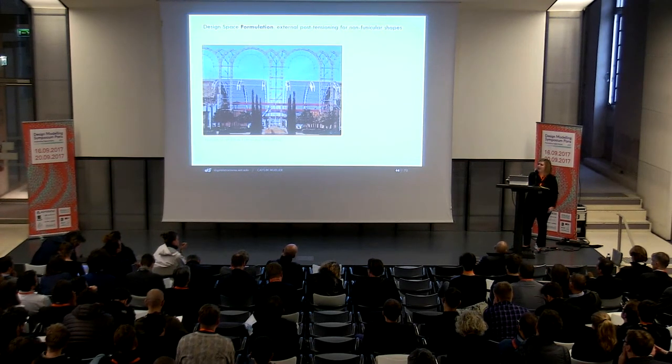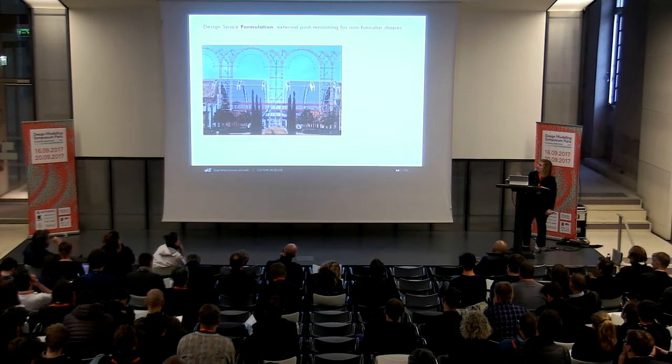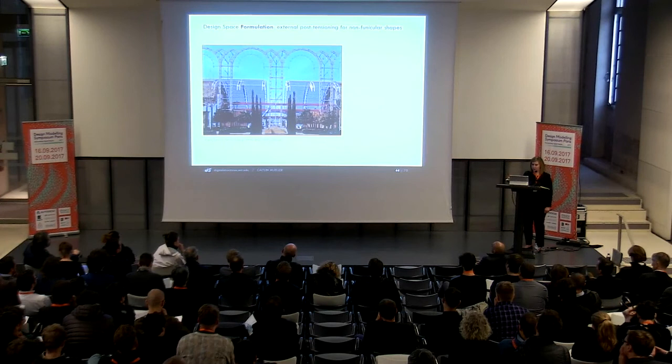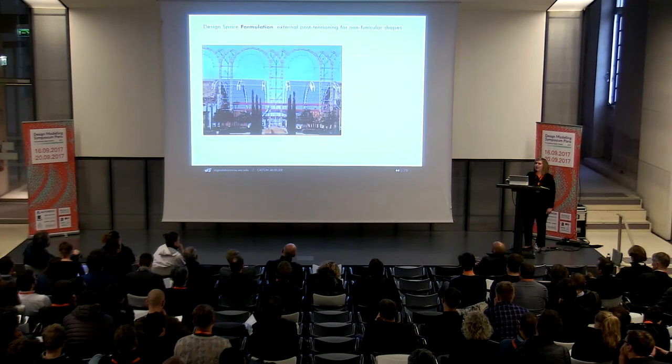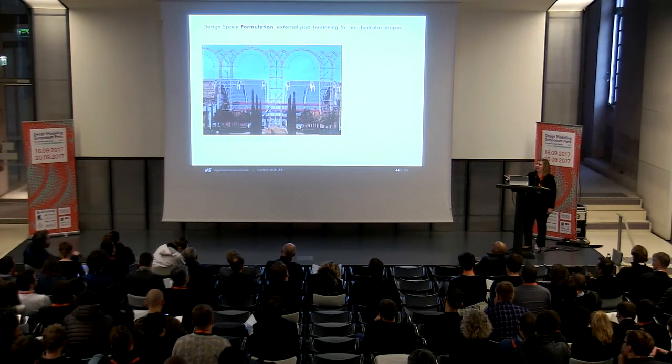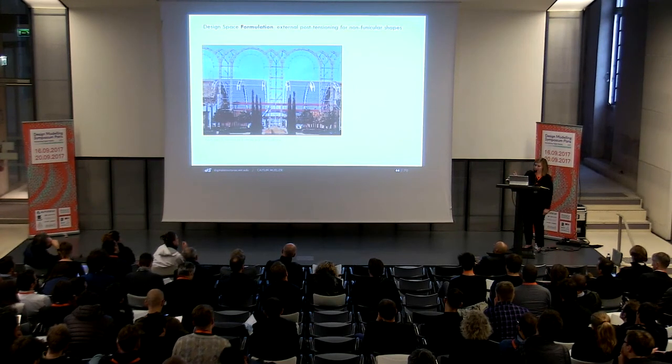And so the way Peter Rice makes this work is by applying this tensile post-tensioning structure in steel to put radial forces into the arch that are large enough that the dominant loading becomes radial, and the circular arch becomes the right shape for the loading that he's applied. So instead of taking loading and figuring out the form that we need to meet the loading, we can change the loading to meet the form that we're interested in.